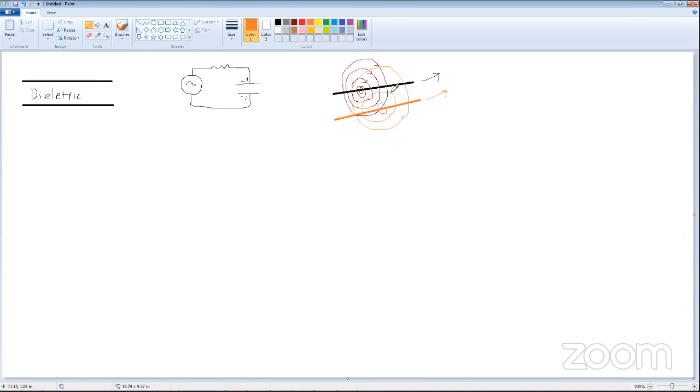Now, one thing that maybe comes to mind is that whenever we're dealing with electricity, we're always talking about loops. So just a single floating wire segment like this isn't a real world scenario, but it helps us have understanding. That's why we discuss it. But keep that in mind. In the real world, you're always going to be thinking about loops. And this concept of an interaction is very important: mutual inductance. When you have traces near each other, they can couple to each other depending on how close they are and how much current they're running. So that's just the main concept we want to take from this.